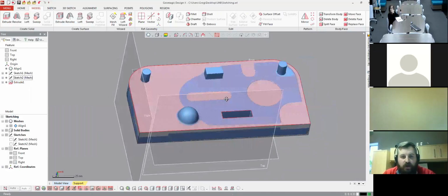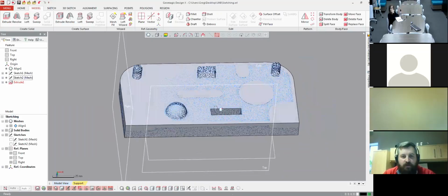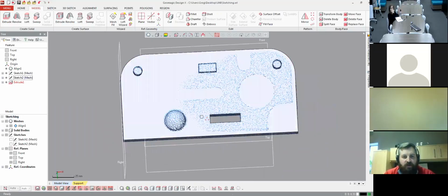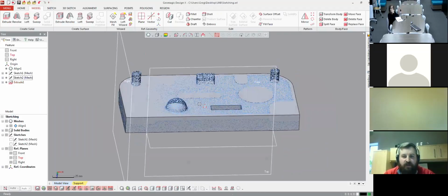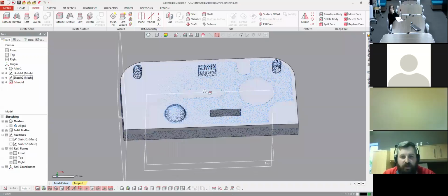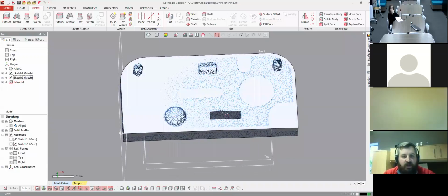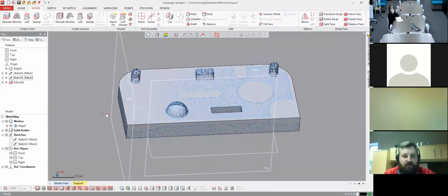Okay, so another function for sketching, if anybody's doing foundry work or things with draft, is the ability to calculate kind of a max or min condition. So we can get an outer limit of something, and there's a function called silhouette when you're building cross sections.